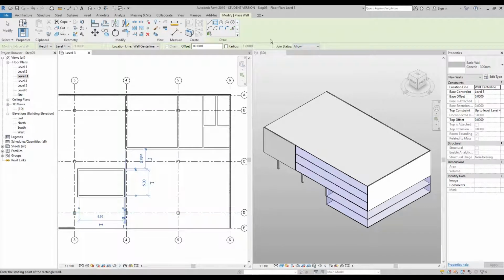Staying within the tool so that your Modify Place wall is still green at the top of your screen, I'd like you to choose the Fillet Arc tool. Once you've selected that, I want you to select the north wall and the left wall, and you will notice that I can have an arc that moves backwards and forwards while hovering. I want this wall to be approximately 2.0, so if I click at 4.54, go to the temporary dimension and type 2.0, my arc will automatically change.